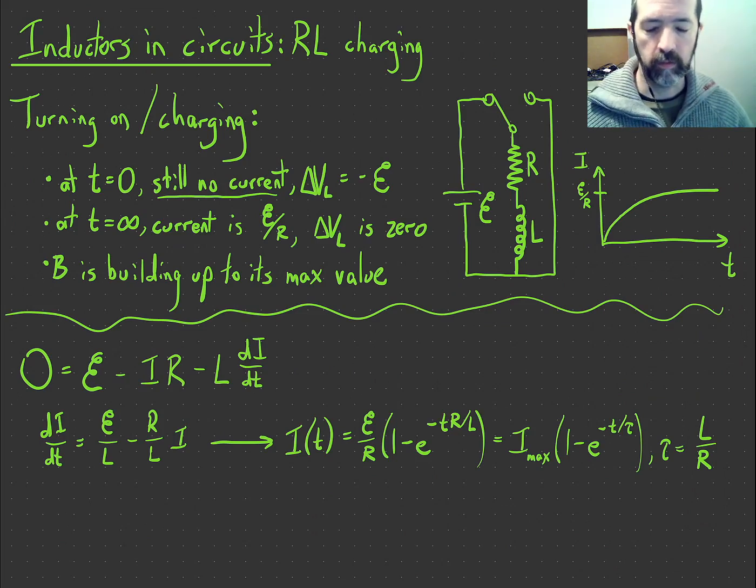And you're most likely to encounter questions about time 0 and time infinity. You just need to remember that at time 0, the inductor maintains whatever situation had just been going on. And you should be able to reason through almost everything that they ask based on that.